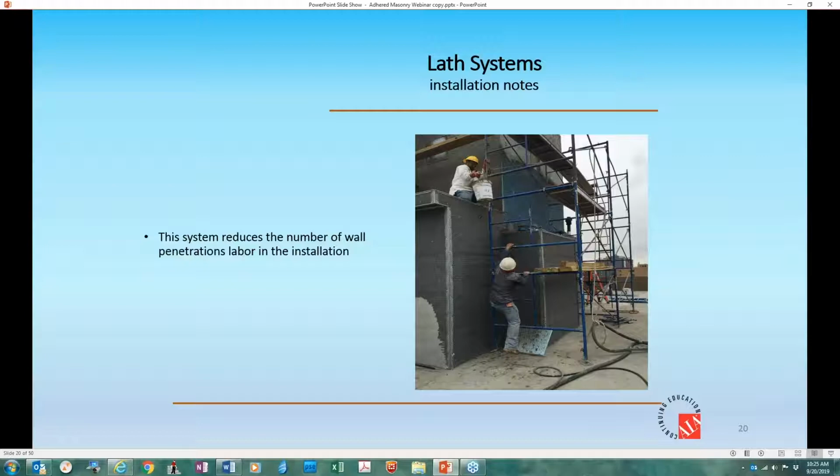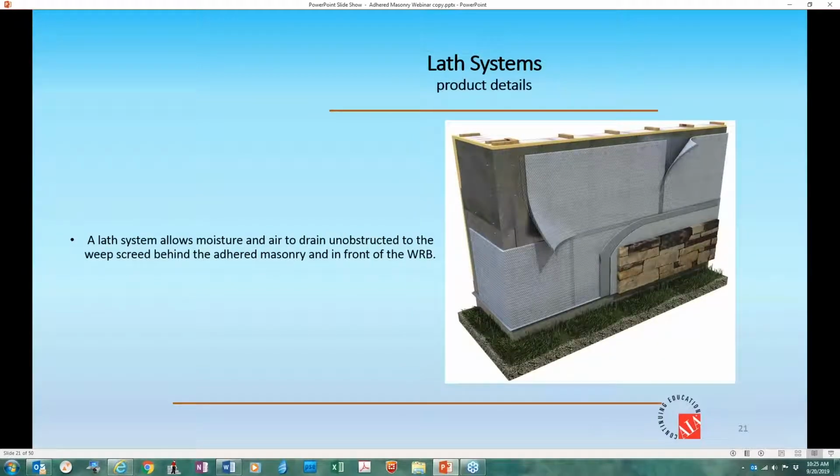When you're installing the 2 products at the same time, you're going to reduce penetrations by approximately 50% because everything's done in one application. And the shingle design will allow the overlap each time the way you need it, reducing any stress of your guys putting it up wrong.